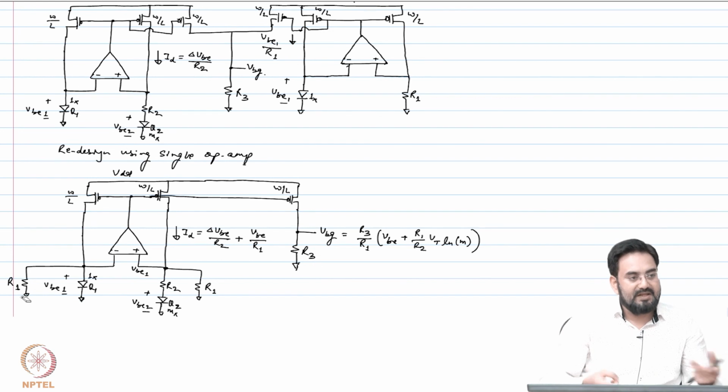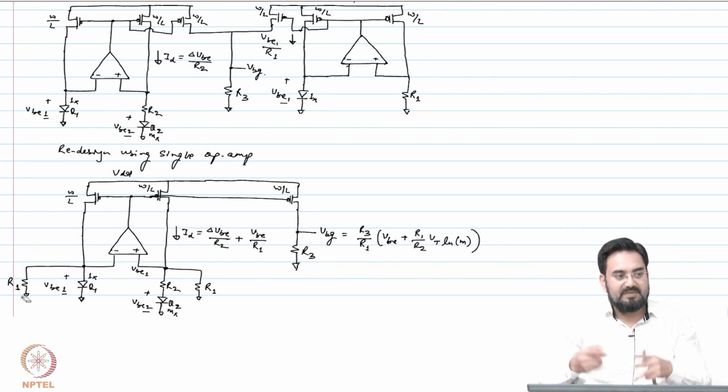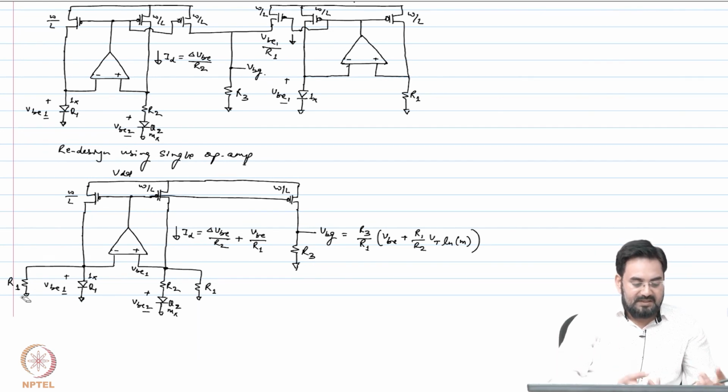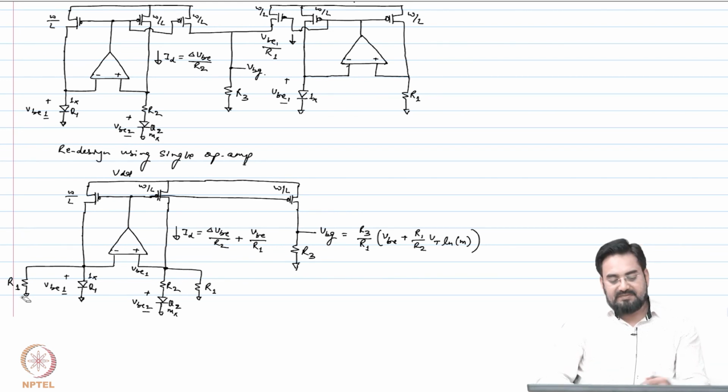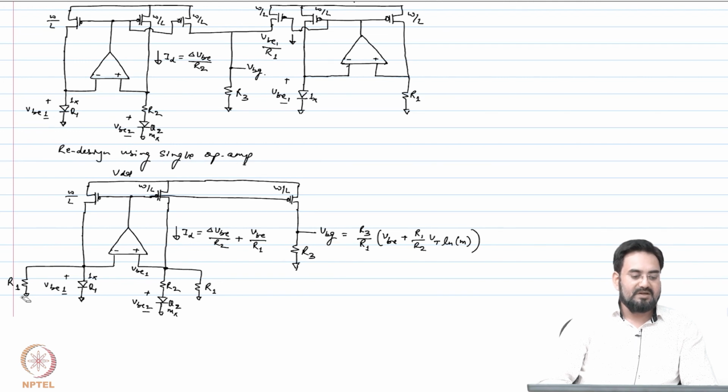Now we have a 2 R1 actually here, so they have to be perfectly matched. So any error between those two or mismatch between those resistors will also introduce error here. So more devices you add, there are more chances of inaccuracy, because if you require matched devices, now matching the more devices becomes harder compared to fewer devices.